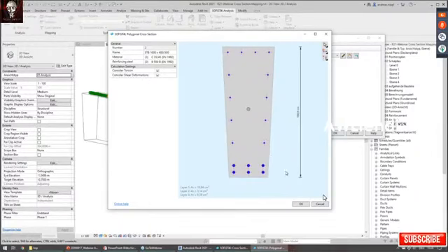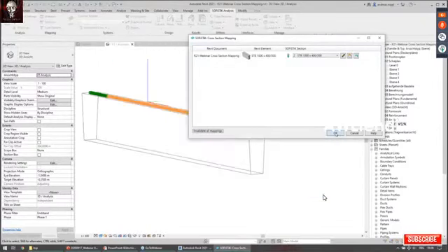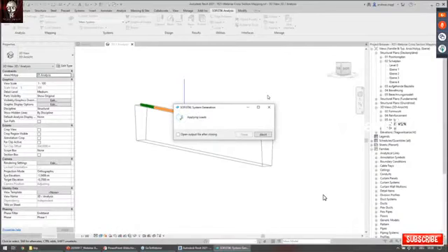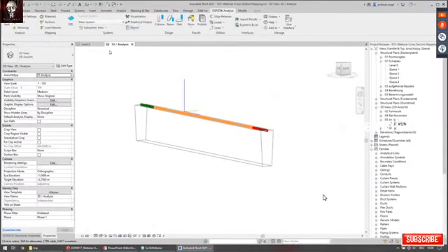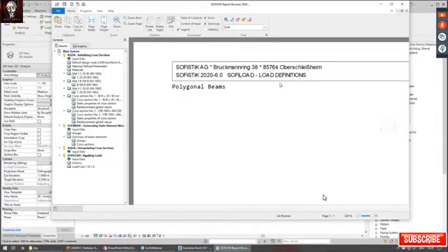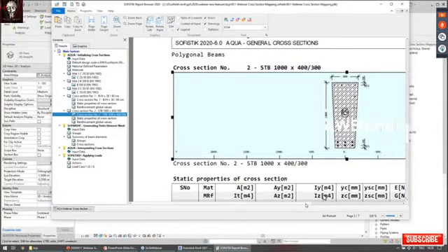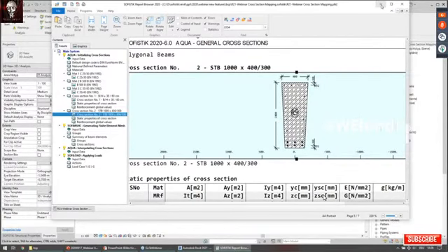You can also change a number of properties. Here you will also see that I have now configured the section with 3 layers. And now I store this section and store the assignment of this section. And now when exporting the system to SOFiSTiK, I just like to mention that you can then see in the report browser that this section has already been generated and is now present in the SOFiSTiK database and can be used for further analysis within SOFiSTiK.